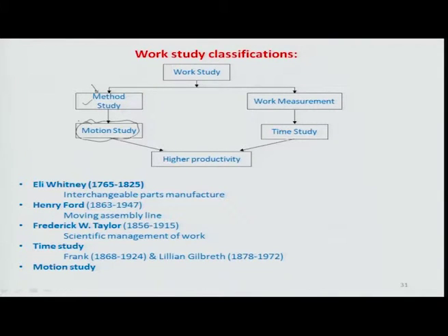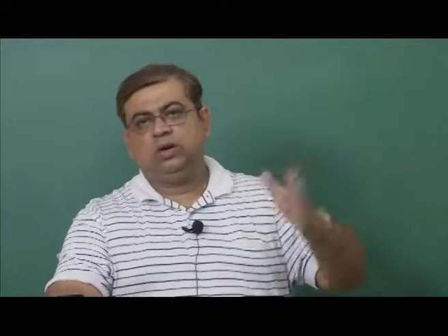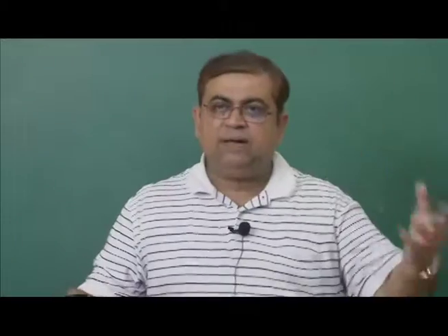Let us say for example, you want to put a window regulator inside the front doors of an automotive assembly. So, obviously many questions come into picture. The regulator is being supplied from offline to online with some kind of a roller conveyor and bins or carriages or racks. So, the operator has to go up to that rack, pick up that particular window regulator, pick up that fastener, pick up a gun which is otherwise carrying, then come back to the vehicle, move along with the vehicle, and place the window regulator from within the door.